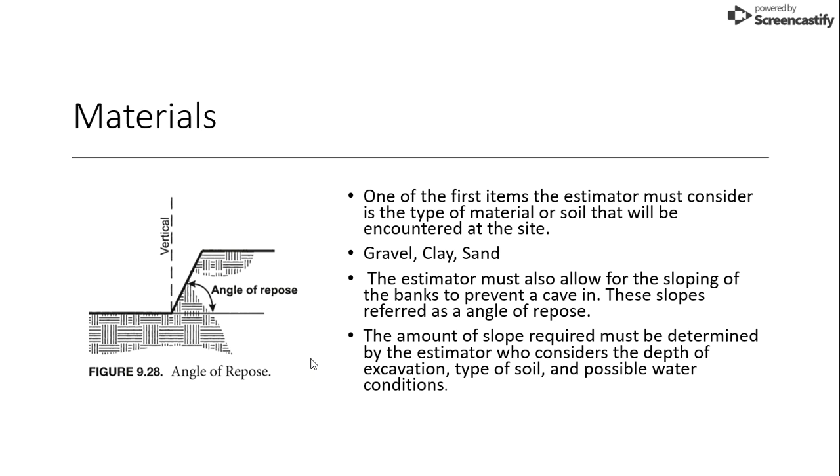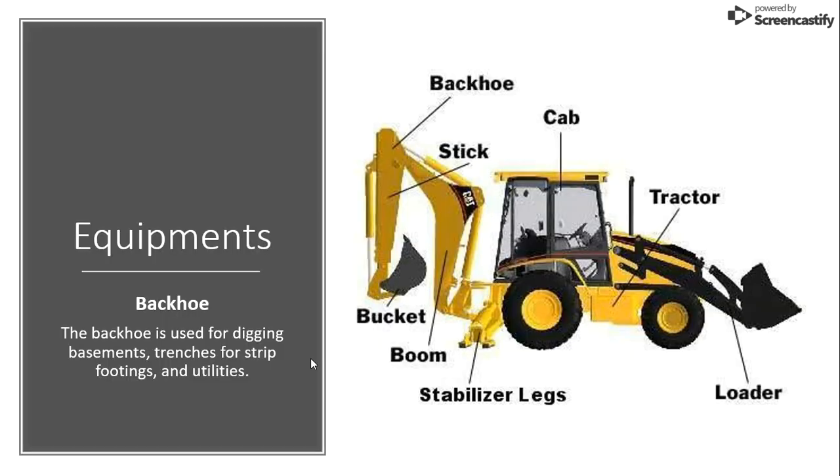The estimator should also allow for the sloping of the bank, to prevent caving and collapse. This slope is referred to as the angle of repose. The amount of slope is determined by the type of soil, the depth of the excavation, etc.